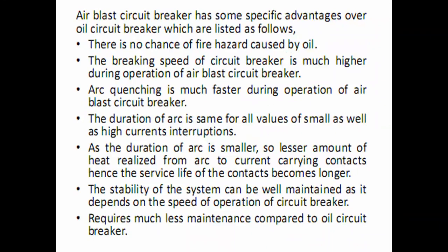The air blast circuit breaker has some advantages over the oil circuit breaker. Number one, there is no chance of fire hazards caused by the oil. In an oil circuit breaker, we basically use oil as a quenching medium and an insulating material. But since this oil is a chemical, sometimes there will be chances of fire hazards. But in the case of air blast, since no external medium is used to extinguish the arc, the chance of fire hazard is very low, or you can say almost nil, as compared to the oil circuit breaker.